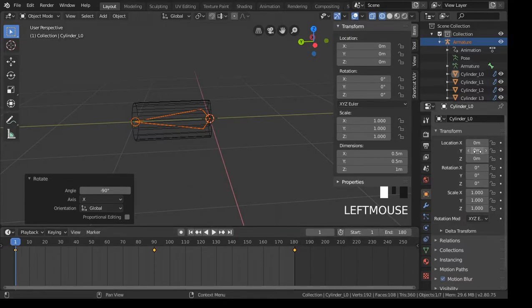The mesh needs to stay at 0, because when it's applied to the uploader, the TMTK compiler will see the mesh being vertical, and it will see the armature at -90 on the rotation X, and when it's doing its compile checks, it will actually rotate this armature on its own back to the 0 position. So when it spits out the object, it'll animate correctly. However, the object in game will be sideways like this, so yourself and your users are going to have to rotate it back 90 degrees. There's nothing you can do about that. It's just the way that the architecture of Blender 2.8 is.